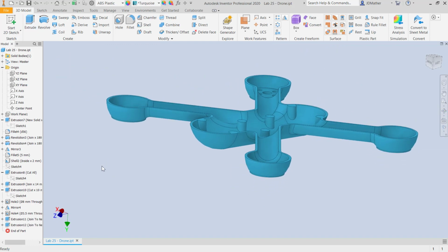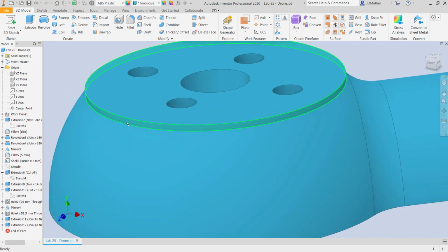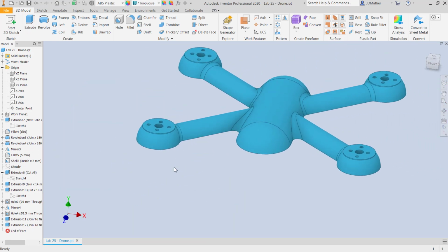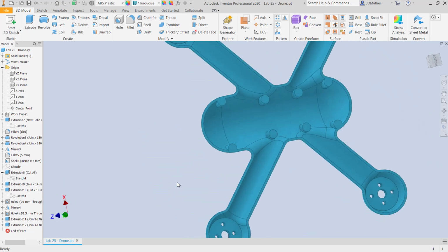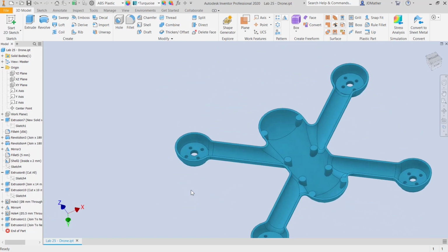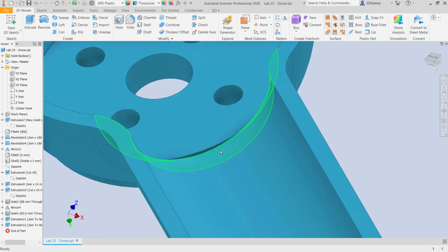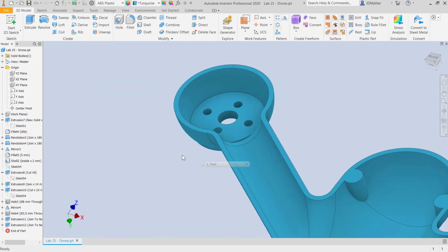Okay. Now I probably should have put draft angle on the sides of this cylinder and draft on these holes so that it will come out of the mold cleanly, but we'll neglect the draft. You can add that yourself. One thing we've got to watch out for now is inside here, the way we made this cylinder, we extruded it and then we cut part of it away. There's a little lip right here that I would like to remove on those 4 locations.